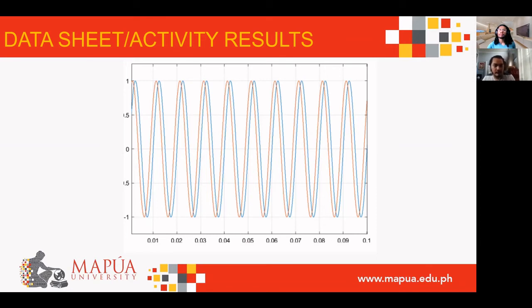It means that for both generators, their signal would change for every half of the period, in which for the MSB, it would change every 0.1 second, while for LSB, it would change every 0.2 seconds. So this is why we can see in this figure that after 0.1 seconds, the MSB has gone back to 0, while LSB is still at 1, which is why the second 2-bit code is 01.